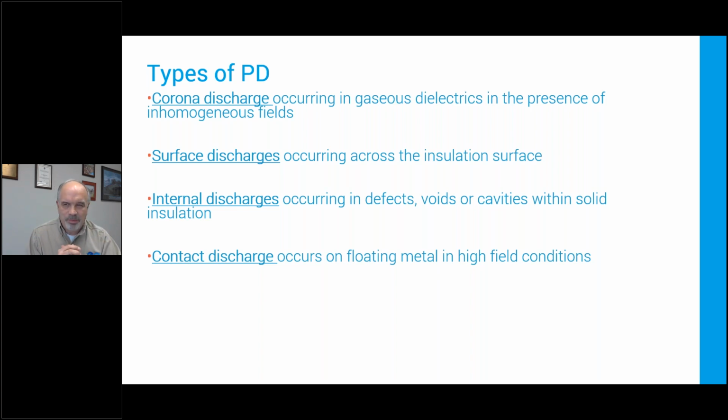That's surface discharge. Internal discharge is particularly painful because it's hard to find. It's hard to see. There's nothing you can inspect. There's no other test you can do other than a partial discharge test. You can take something apart, clean it, service it, put it all back together, and it can blow up the next day. So you've got to be able to detect that. We'll talk about how you detect that.